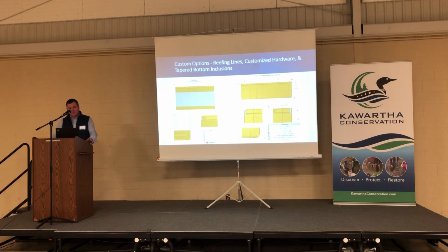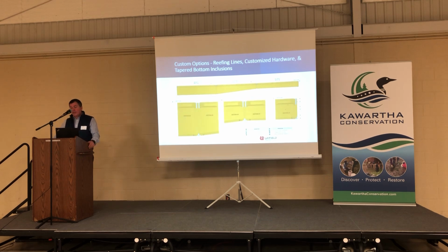Okay. Some of the different options, as I mentioned earlier: reefing lines are very popular, and that allows you to hoist up and down the curtain to allow it to contour to the bottom as best we can. Additional reefing lines are possible, certainly a customizable item. And in some cases, we can taper the curtain, so it will contour to the depth, starting from, say, the shoreline, a shallower type curtain, and then gradually increase the depth according to the installation.